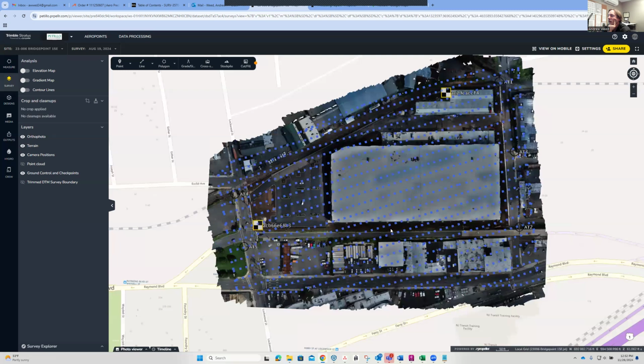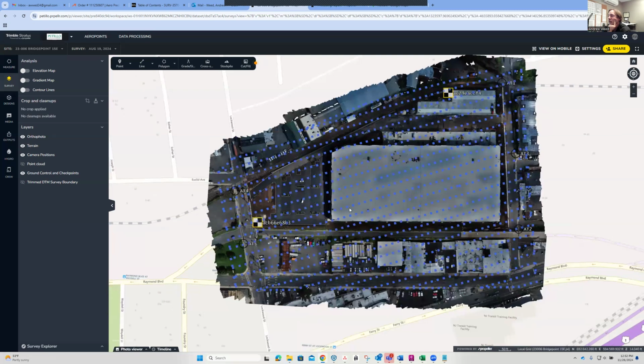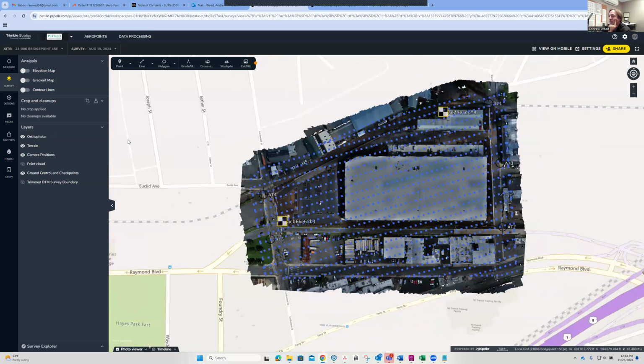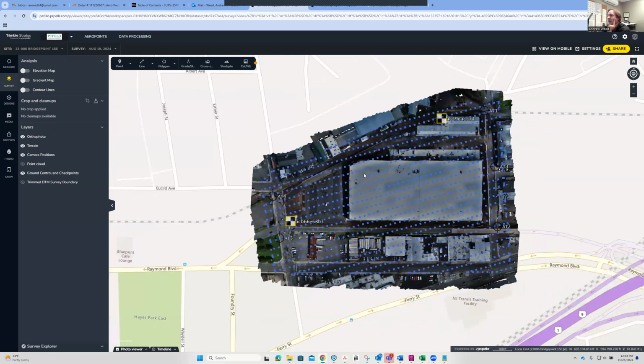So we want our as-built data and any drone data we collect to live in the same place, basically as the entire project. That way we're not drawing the as-built over in space and then trying to move it on to make sure everything's inside the property lines where it's supposed to be. So this is based on project coordinate systems. Now, they don't have to be any sort of state plane coordinate systems. These are just a local grid. We could say that this intersection of road is 100 north by 100 east. It doesn't matter as long as you provide coordinates for these points.